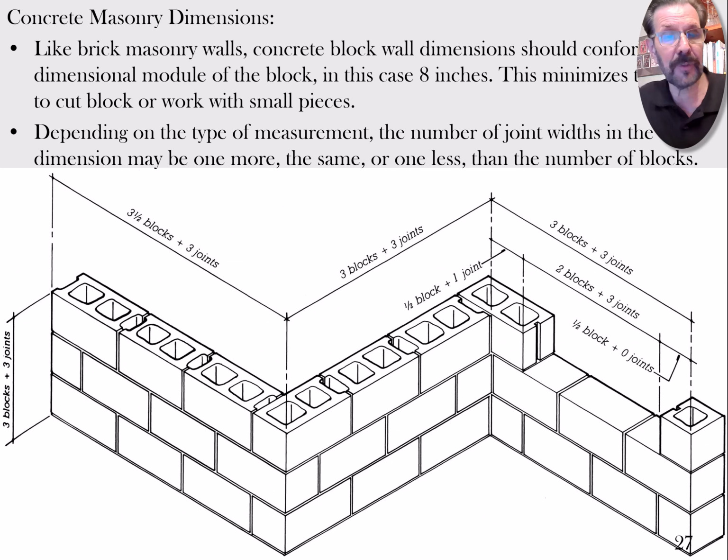Now we're laying out the blocks just like when we were talking about the brick. We tend to build the buildings, when we're involved in general in construction, but particularly when we're dealing with masonry and brick, in 8-inch units. So all the windows and doors and the lengths of walls generally are some unit of 8 inches. It's just very, very common to do that, because otherwise you raise your costs when you have to cut a whole bunch of blocks.